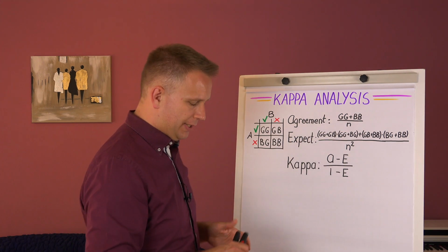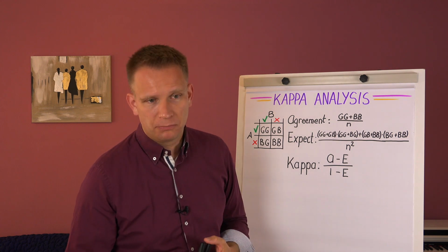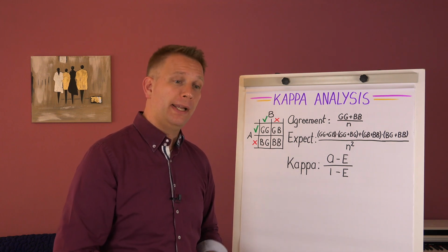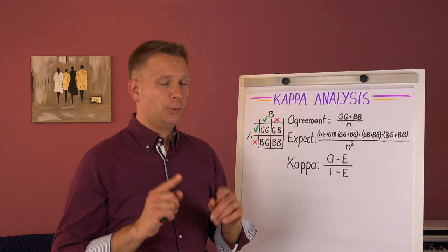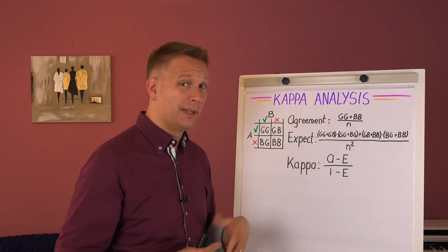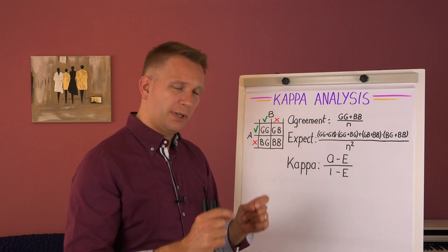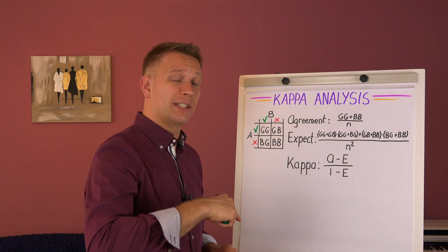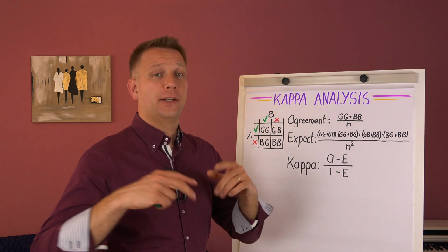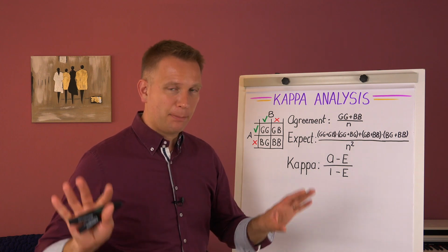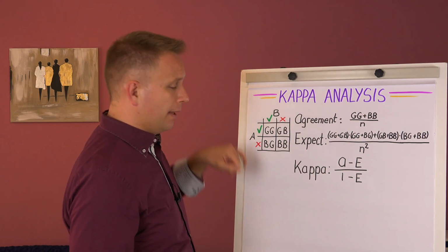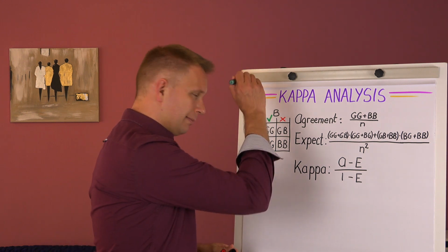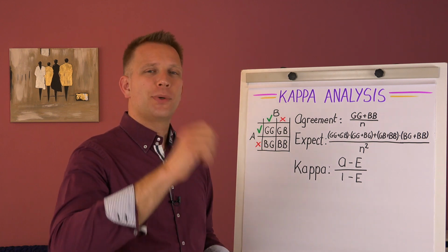So the way that you use this table is you will take, for instance, 20 different products. You will hand them to operator A and to operator B, the same 20 products preferably, because otherwise it's very difficult to compare. You know which products are which, what the other person said; operator B should not know what A said, right? They do not converse and make an answer together, separate assessments. And then when your first product is good, you just put a tick there, you get your first one, and like this you count all of them.